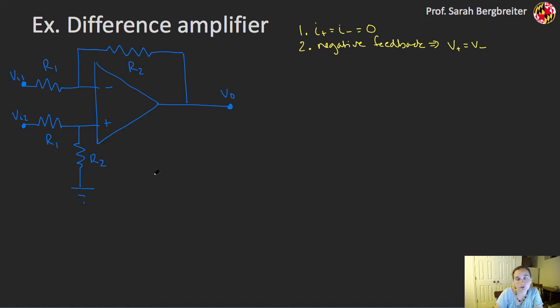And based on that, I'm going to have a general approach for how I tackle these circuits. So I'm going to try to figure out what's going on at the non-inverting input of the op amp, try to figure out what voltage that is, and then apply that voltage to the inverting input of the op amp, and then do some basic Ohm's law or KCL equations to determine what the output is in terms of input. So let's start with that.